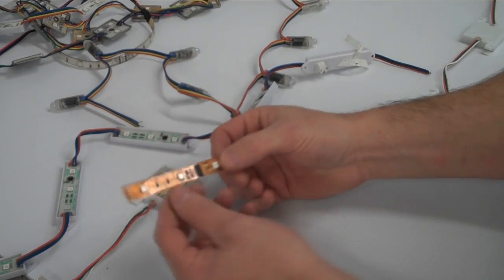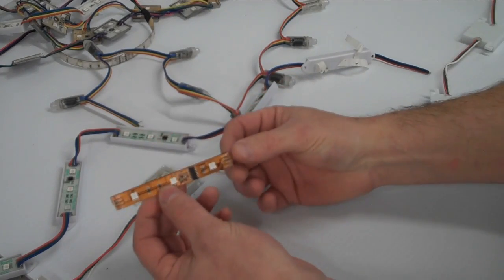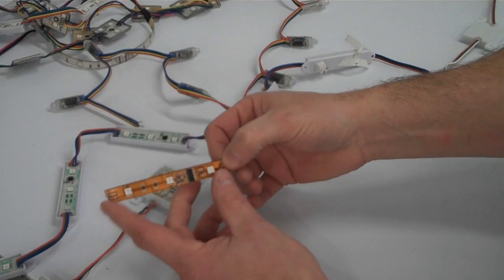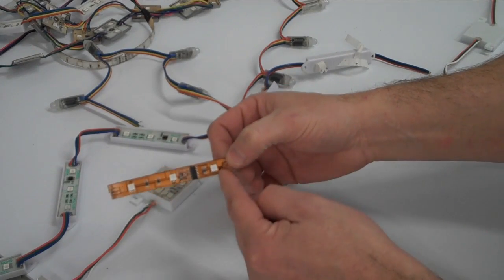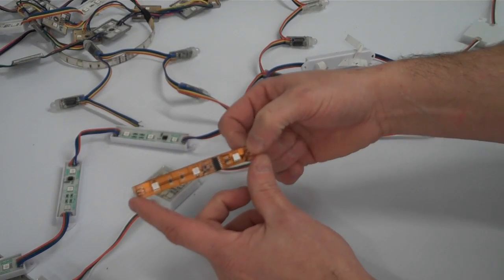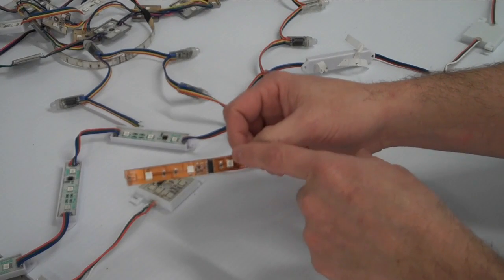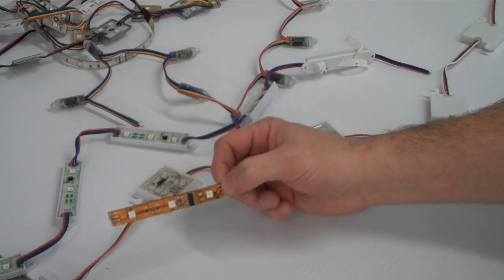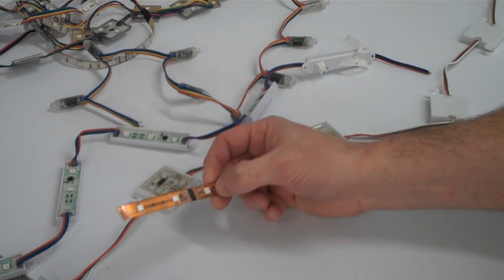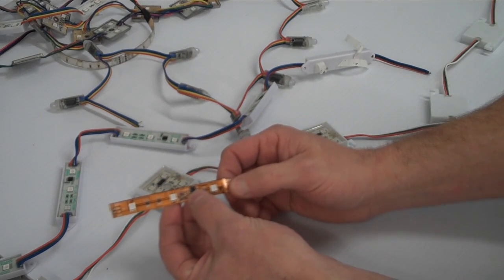There's a computer chip on each strip. Each section of strip, which is usually about 100 millimeters long, is individually a pixel. So these 3 LEDs, along with this computer chip, comprise 1 pixel, or 3 channels within your particular sequencing software. Now, one of the things that may confuse you is that pixels have no addresses.